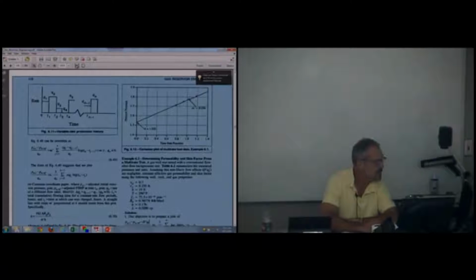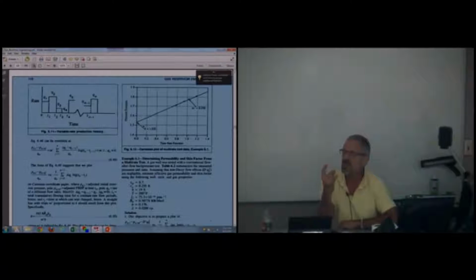Sorry, that was your initial pressure minus normalized, that was your rate? Yeah, delta pressure, so I'm already trying to jump ahead and say delta pseudo pressure. Delta normalized pressure divided by the rate. The leading term of the delta pressure is initial pressure minus the pressure at that time for that flow rate.